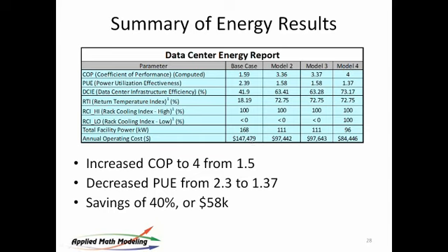That's a $58,000 delta. And as I said earlier, users may not feel comfortable predicting the actual cost of operation. They may want to use percentages and say, Mr. Customer or Mr. Operator, I think I can save you 40% by doing these changes. So on a budget of $150,000, 40%, you can do your own ROI. It happens quick. And all we did here was switch things off. Now, we probably also put backflow preventers in place, but that's just sheet metal, louvers, not complicated, not expensive. And also here we put some curtains in place, which aren't expensive either.